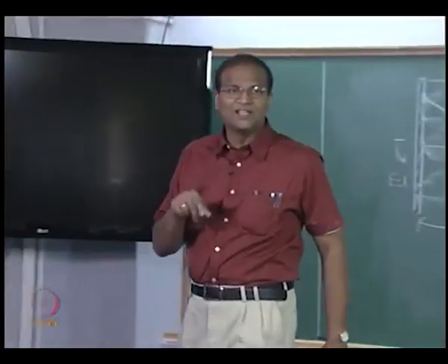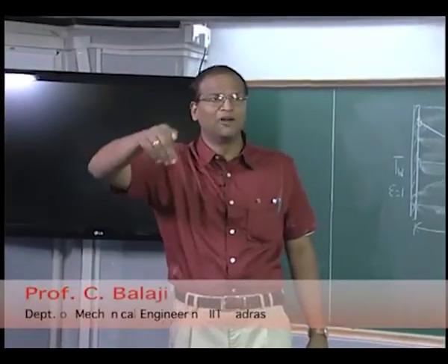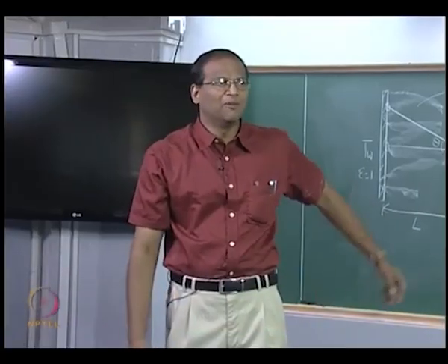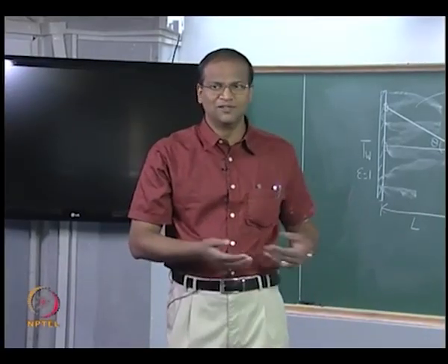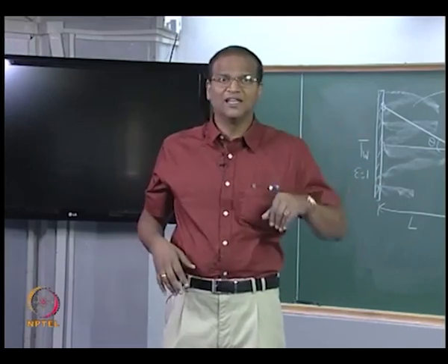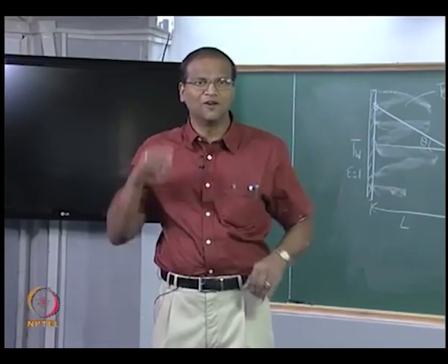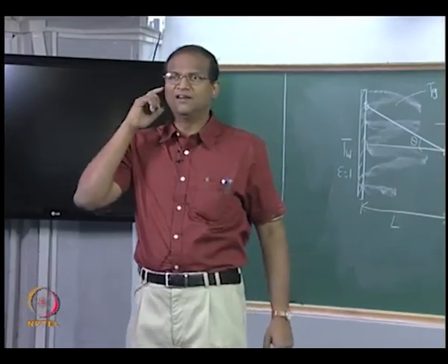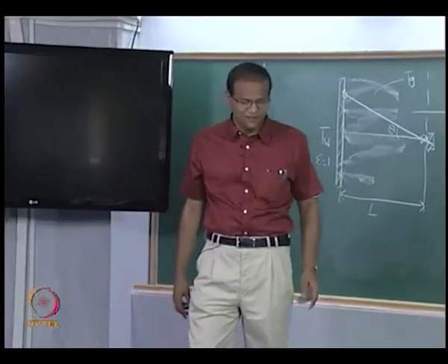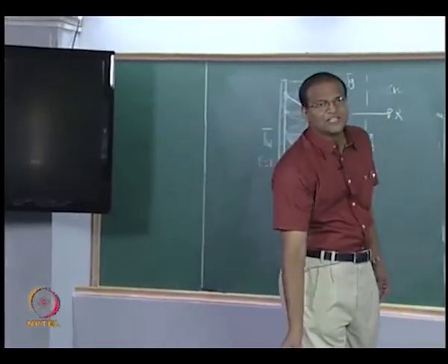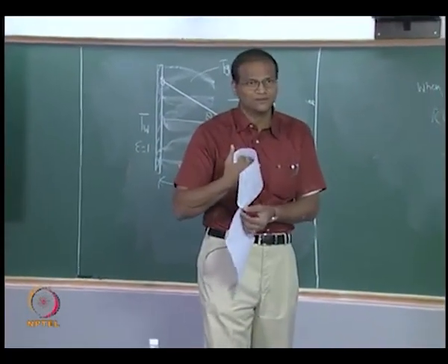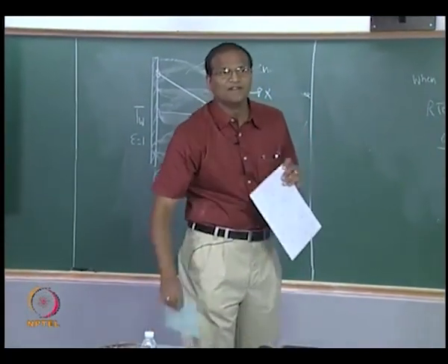But this is because the radiation is coming from a black body at 5800 Kelvin, you do not worry about epsilon lambda Ib lambda of Tg because the ocean temperature is only about 300 Kelvin or something, okay. But in the general case when the gas emission cannot be neglected, then we are in trouble, the integration becomes very difficult if you want to evaluate the heat flux. I will introduce the exponential integral function, I will give you tables and you have to use these tables to compute the heat fluxes, okay.